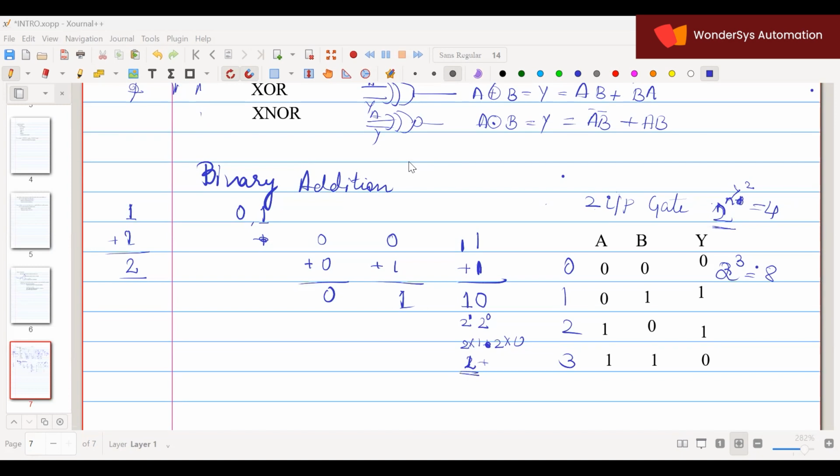No, ma'am. See, whenever you write the ladder diagram, basic gates are really important, the AND and OR operations and all. Whenever you're not able to solve any combination a programmer has given to you, using these basic gates you can make it easier.